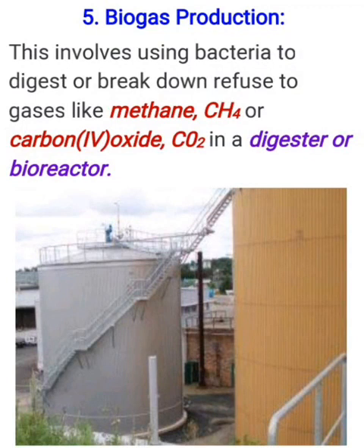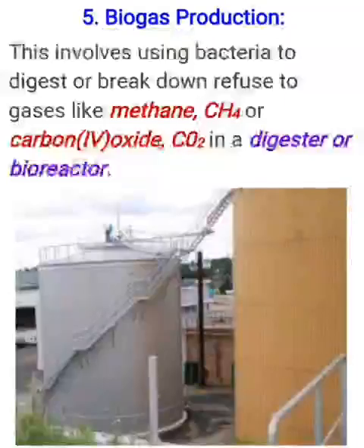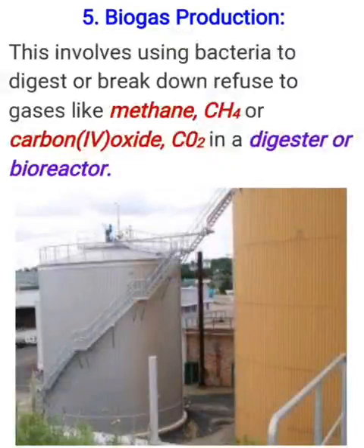That tank you are seeing, the shorter tank, is called a digester or a bioreactor. And so what normally happens is you can collect waste, especially biodegradable waste, and put it inside the bioreactor. When you load it inside the bioreactor, then you now introduce a culture of bacteria. It could be aerobic digesting bacteria or anaerobic digesting bacteria. Any of them. We have two types of digester, aerobic digester and anaerobic digester.